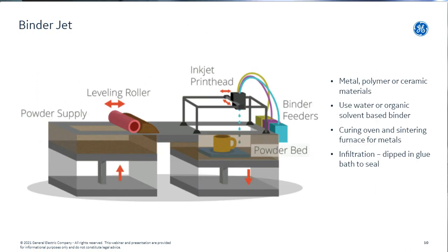The third technology I want to introduce here from the hazard point of view is binder jetting. Also, that is an interesting way how to do it. So you also have there a powder bed where you build up and level layers of material that you want to print. As I already said, it can be metals, it can be ceramics. But instead of melting it or heating it up with an electron beam or a laser, you utilize a printer system, like you maybe have with your inkjet printing system at home, a little bit more sophisticated. What you apply here is more or less a resin that then glues together all the particles.